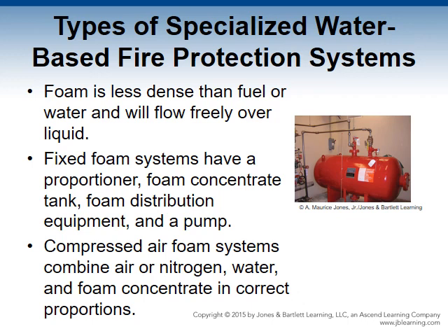which covers the design, installation, inspection, testing, and maintenance of fixed, semi-fixed, and portable foam extinguishing systems. Except it doesn't deal with deluge foam, water sprinkler systems, combined agents, mobile foam apparatus, Class A foam systems, or obsolete chemical foam systems. You would have to look at NFPA 16, NFPA 1901, and NFPA 1150 to cover those exceptions.